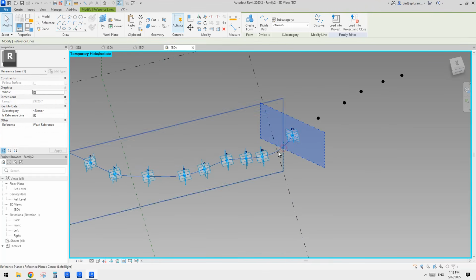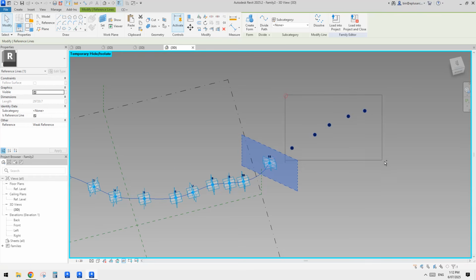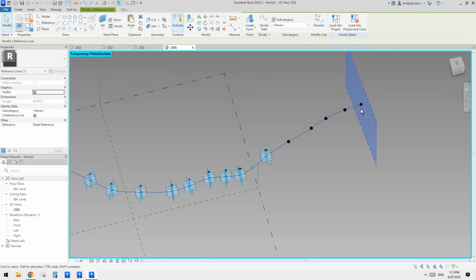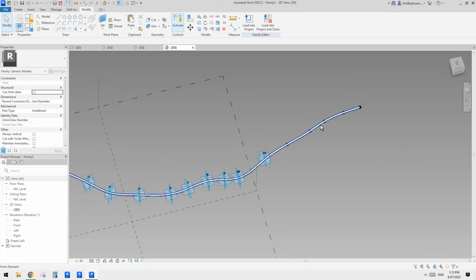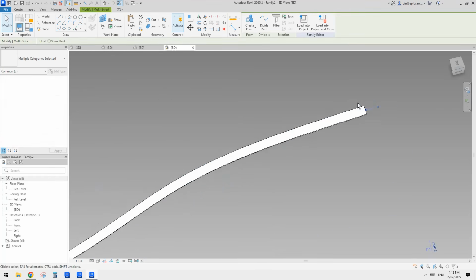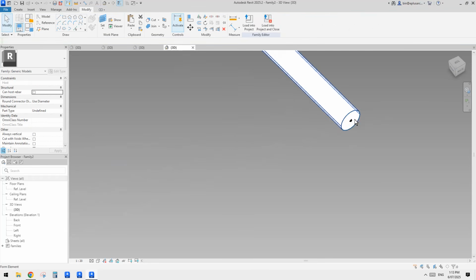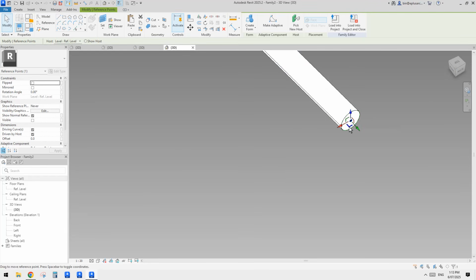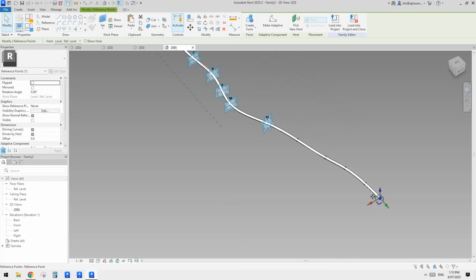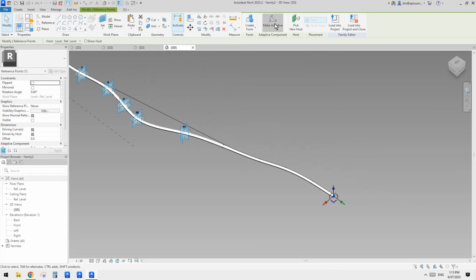So now select this spline through point, and then I'll try to select all these, and hopefully, you can see it will continue this spline, which means if I type HR, this form will also continue. Because the profile of that, on that end, the point will always stay. Yeah, where is it? Oh, there are two. Sorry, that's another point. So this is an adaptive point. Oh, looks like I forgot to change it to an adaptive point. Sorry. Let's just do it now.